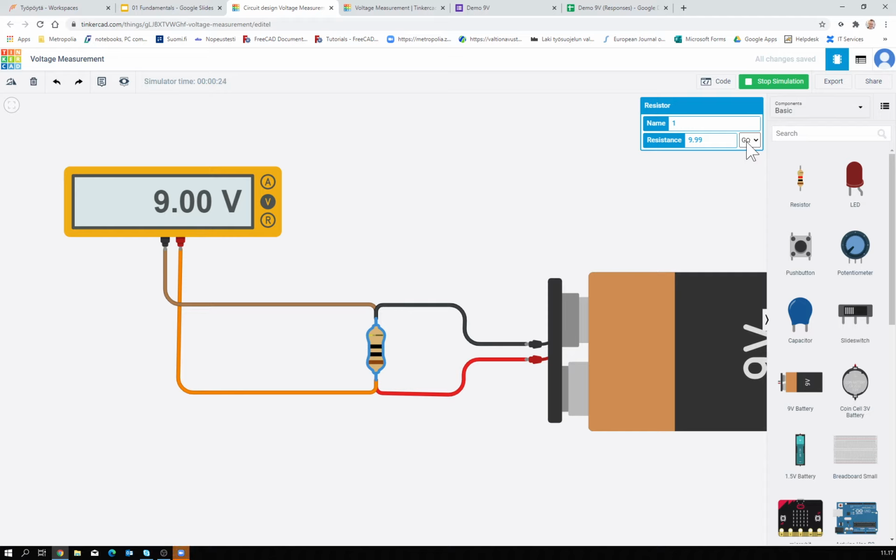On a 10 mega ohm resistor, if there are dust particles on top of it, it already changes the resistance. So practically these giga ohm resistors are as good as open circuits. That's the easiest way. Another way would be to disconnect the wires and reconnect them again.